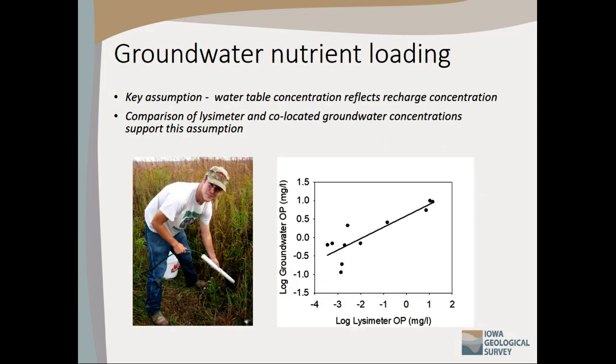So if we want to say something about loading rate, though, we need to say something about the water flux. We're going to get groundwater recharge from the water level rise and the specific yield. What's the concentration we can pair to that to get some idea of the nutrient loading? Well, one of the assumptions I made in this process is that the water table concentration is associated with the recharge through the soil profile. You know, we can probably debate that assumption, but that's a simplifying assumption.